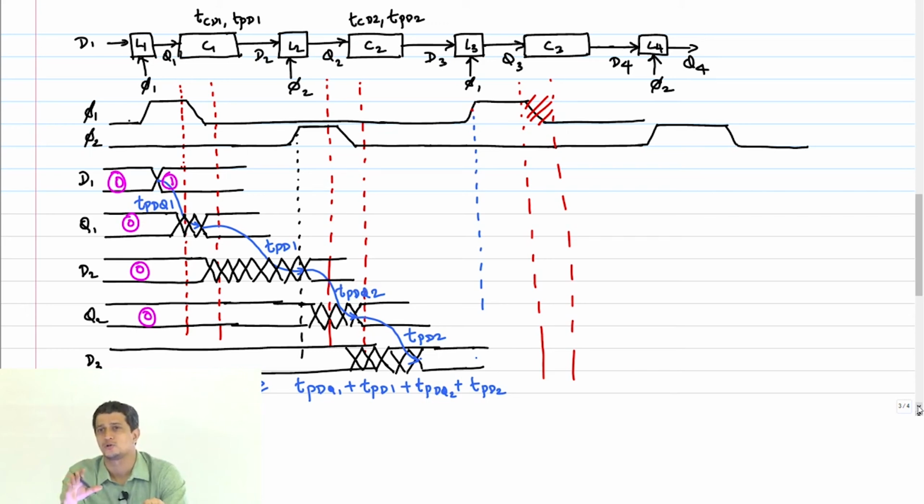Right now we are saying it should not go after the falling edge. So it cannot go all the way till there, correct? That depends on the splitting of the combinational block, so basically on how much time you are borrowing.